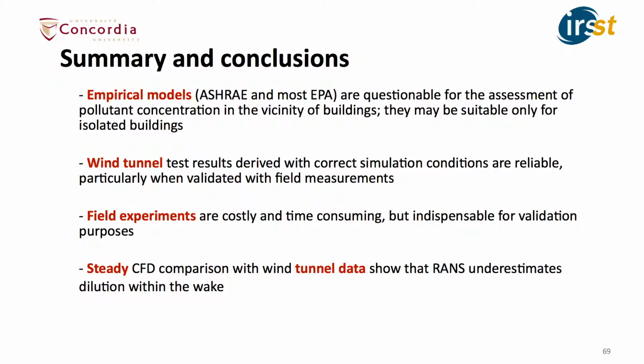models, ASHRAE, EPA. They are questionable for the assessment of pollutant concentration in the vicinity of buildings. They may be suitable for isolated buildings, but not for many more than those. Wind tunnel test results derived with correct simulation conditions are reliable, particularly when validated with field measurements. Field experiments are costly, time-consuming, but absolutely indispensable for validation purposes. Steady CFD comparison with wind tunnel data show that RANS, the Reynolds-averaged Navier-Stokes equations, underestimates dilution within the wake area.